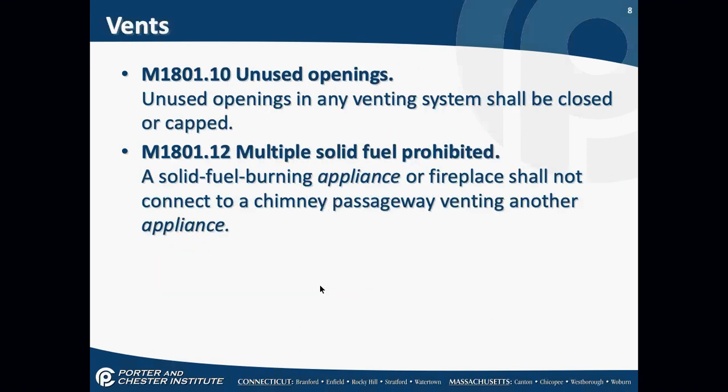Okay. Unused openings. Any unused openings in any vent system need to be closed or capped. So in other words, if you remove a hot water heater and start using the boiler for the hot water instead, we've now reduced the number of appliances. You can't leave that opening in the chimney uncapped.